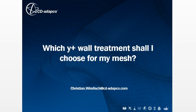In this video I will show you how important it is to choose the right combination of near wall mesh and Y plus wall treatment. At the beginning we will start by taking a look at the theory of turbulent boundary layers. After this we will simulate turbulent boundary layer flow in a channel, and I will show you how different Y plus wall treatments behave for different mesh resolutions near the wall.